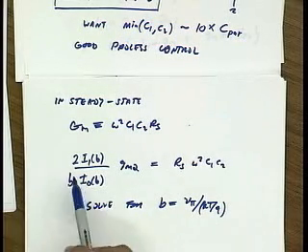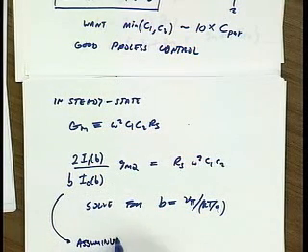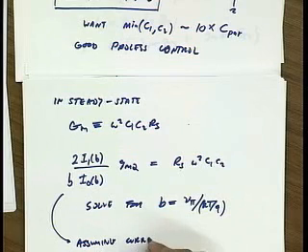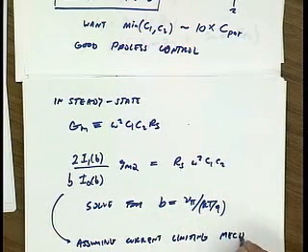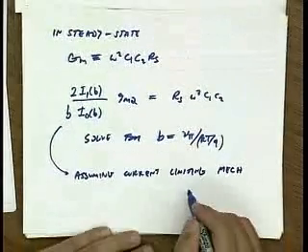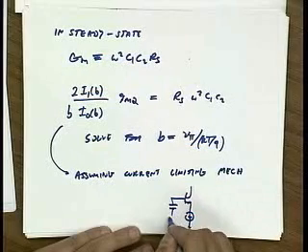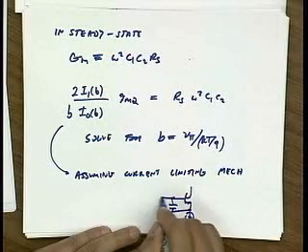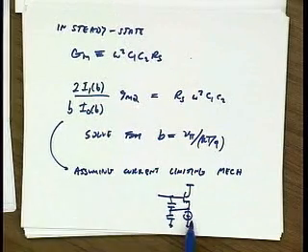And notice, the moment I use these equations, I'm assuming that there's a current limiting mechanism. And here the natural current limiting mechanism would just be to bias this up with a current source, or a large resistor.